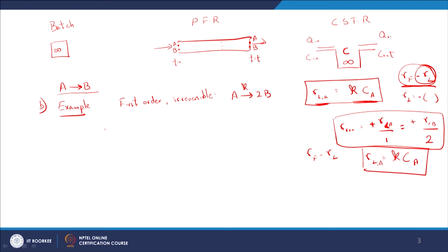So, let us see what we are up to next. We are obviously going to apply this on the batch reactor, for the mass balance on compound A, and you know the system boundaries, right. So, the mass balance is, as we know, dCA by dt equal to rate of formation of A minus the rate of loss of A. This is what we derived for our basic batch reactor a couple of sessions ago, the last theory session anyway, right.